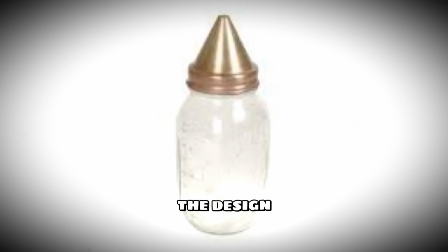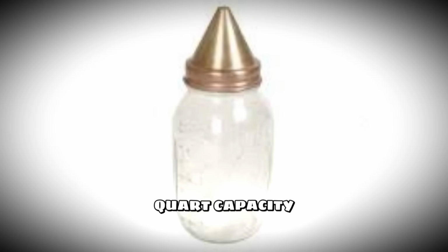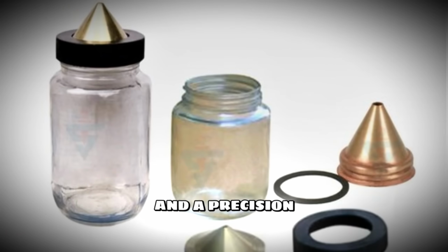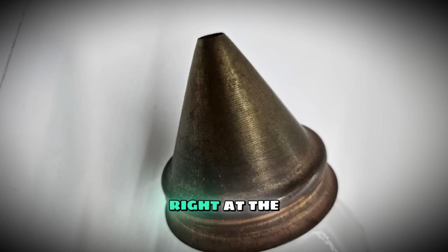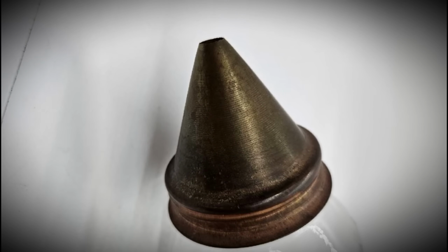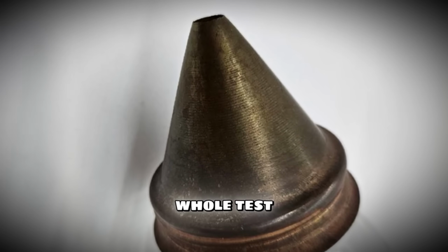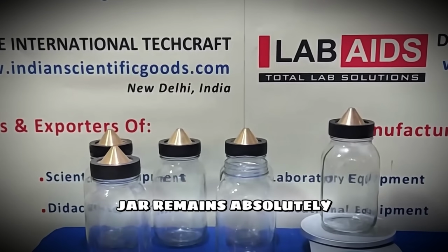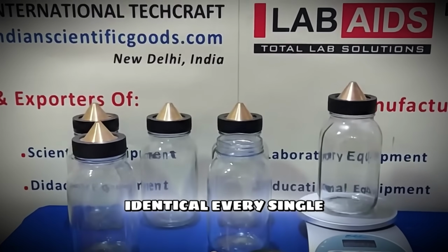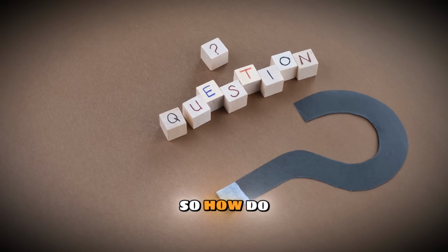Let's look at the design. It consists of a glass mason jar, usually a 1-quart capacity, and a precision-machined brass conical top. Notice this small hole right at the apex of the brass cone? That's not a manufacturing defect. That is the secret to the whole test. That tiny hole allows air and excess water to escape, ensuring that the volume of the jar remains absolutely identical every single time you fill it. Precision is everything. So how do we use it?